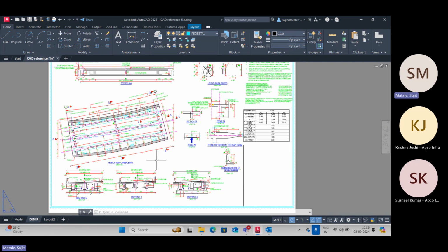For that, when I went to my professor, I said Sofistik has a nice graphical user interface. If there is an error, Sofistik returns an error stating there is a problem in such and such line. OpenSees is such that it won't give you any error. It is a black window that simply closes down. But it is widely used in the research domain because it has very high capabilities to handle the non-linear stuff.